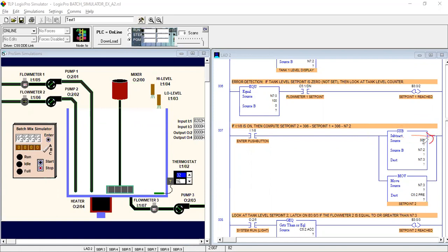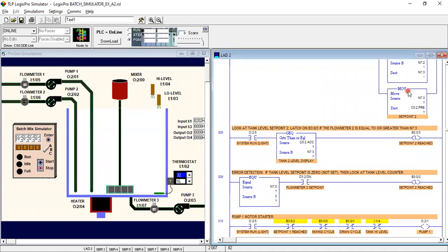Okay, the subtract instruction has source A and source B, and the destination value. So for our source A value, we manually put in 306. You can take any other value you want. Okay, and in the source B we have to connect another integer value, and in the destination we have to put a different integer value, a new integer value. And in the move we have to connect one parallel instruction, which is the move instruction.